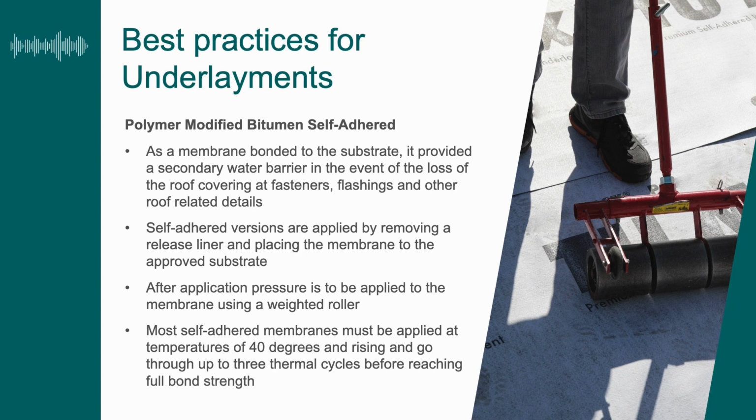And these membranes are pressure and temperature sensitive, so after you install it, you have to apply pressure using a weighted roller, such as the one pictured here. And most self-adhered membranes have to be applied at a temperature of 40 degrees and rising and go through up to 3 thermal cycles before reaching full bond strength.